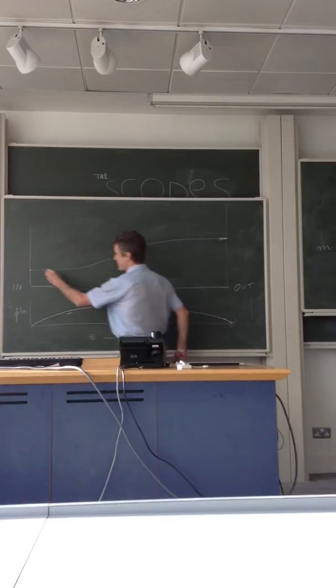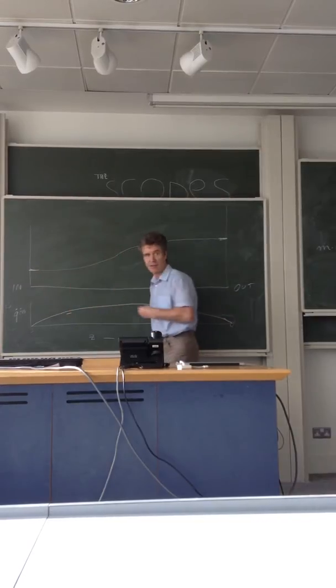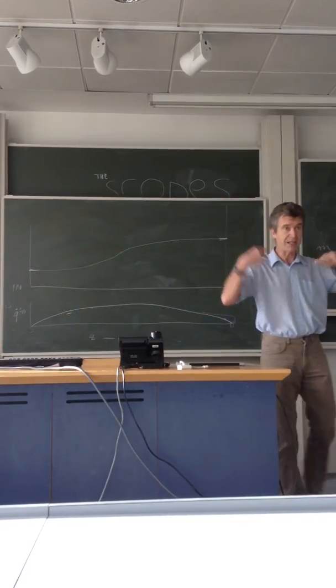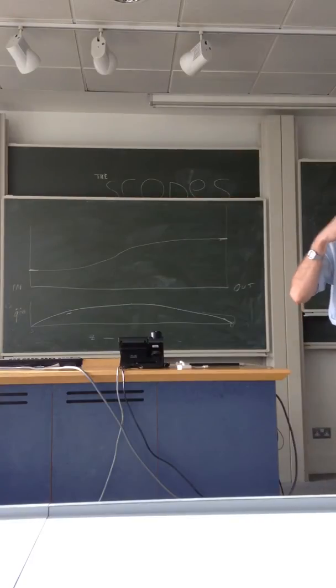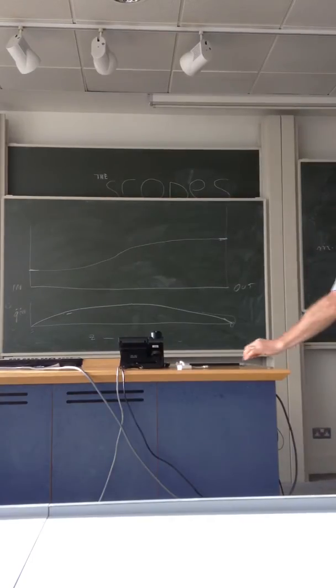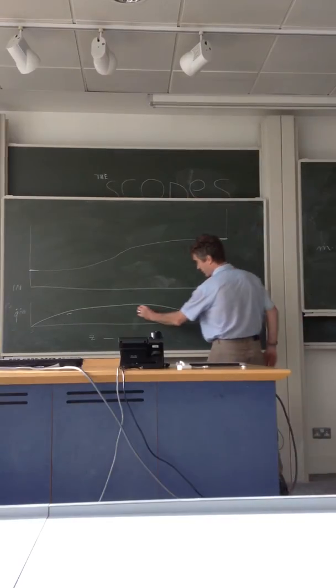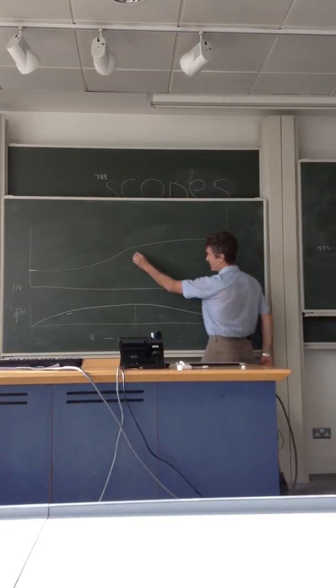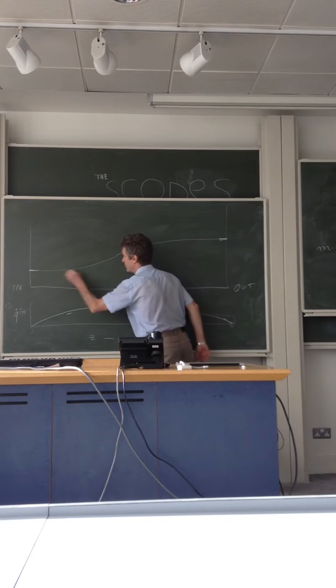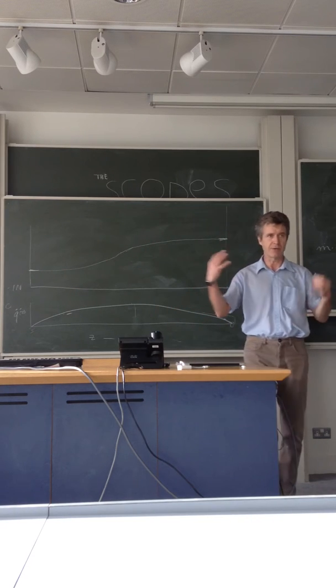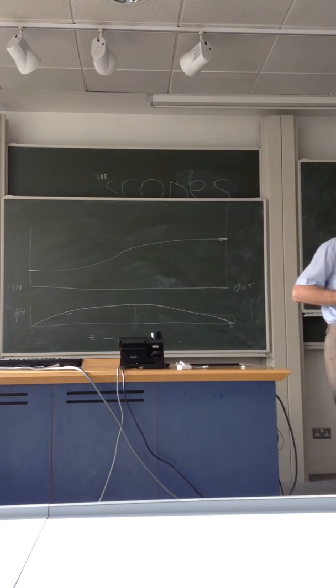So at either end, which the maths bears out as well, it does the same. So the slope, the rate of change of temperature, is proportional to the local axial rating, obviously. By the same argument, where the rating is highest in the centre, we've got the highest slope. So it does that, and indeed it is a sine or a cosine. It's a trigonometrical function, obviously, just coming from integrating that. So that's the coolant temperature.